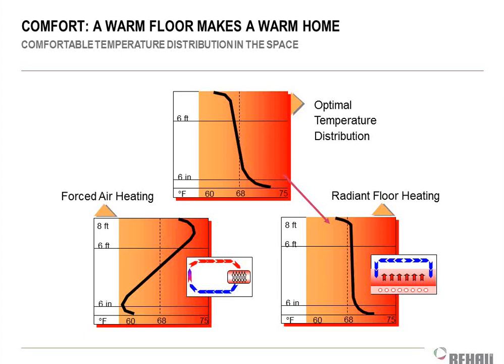If you were to put a radiant floor in your house or in your commercial building, that floor is going to be shining on you with infrared radiant heat, warming you up. Additionally, the radiant floor is emitting that heat and shining on all the surfaces. So it's shining on the wall and the desk and the chair and everything else in there, warming those things up, making them re-radiate back to your body. So we do a significantly better job of being able to heat you with radiant heat than we do by heating up the air. And it's such a better job that you're actually able to lower the temperature set point